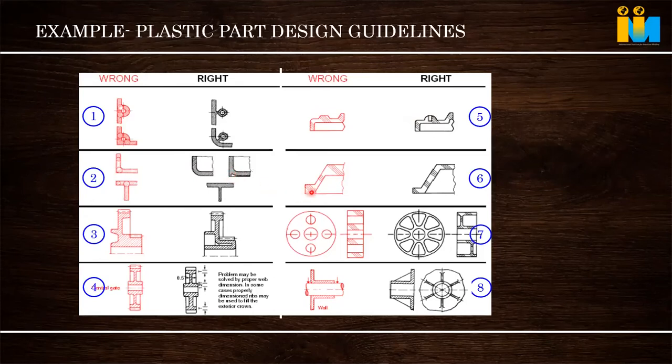It is like this. And see, there is a huge wall thickness change happening here. Gradually we are doing it. Here also, see, there is a huge wall thickness. So sink marks, blowholes, everything can come. And higher injection and holding time, loss in cycle time, raw material wastage, process wastage, everything. The weight of the part will go up, transit loss will be higher. Since weight is higher, our product cost, transport cost, everything goes up. Everything is related. And the quality of the part also suffers, with internal blowholes.